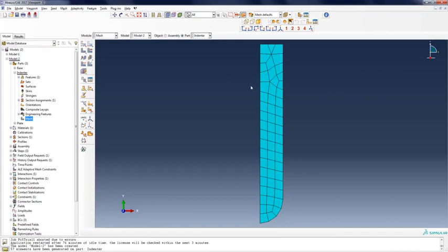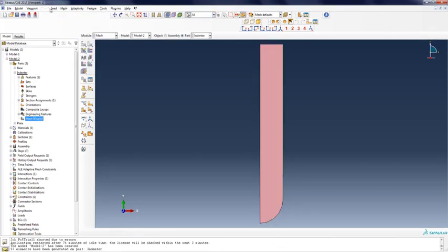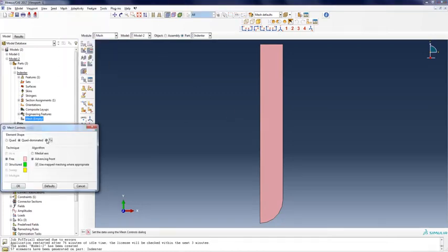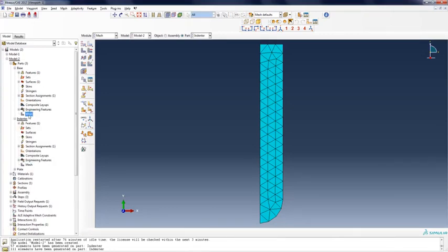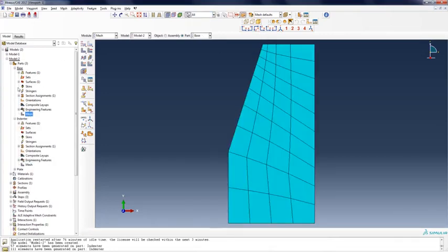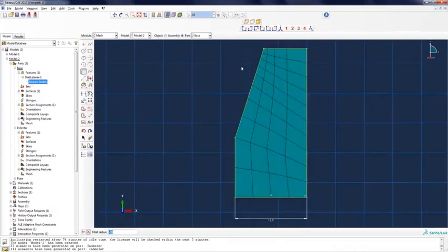And it creates such an irregular mesh. So of course we can change the element type. In mesh control, we can make it triangle, more uniform. Okay, let's stick to this one. Now we've meshed our indenter, and we need to modify our base, because here we have sharp corners and we want to make it smooth. So we go to the section sketch. Okay, we create a fillet.